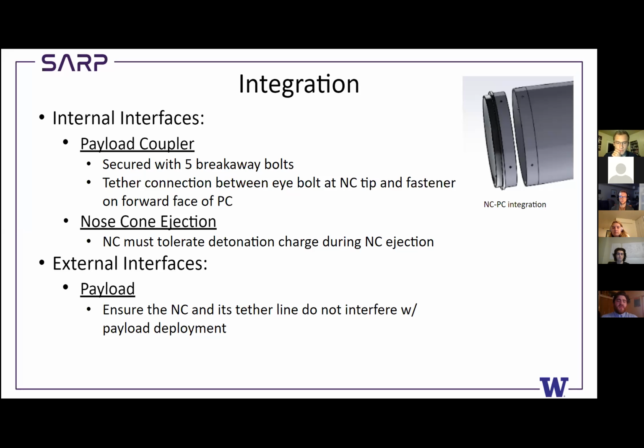Now, integrating with Nosecone ejection, the only design requirement we need to make really is ensuring that the Nosecone will withstand those pressure forces. As well, this isn't one of the bullet points, but it should be: make sure that the bolt holes on the Nosecone won't break or fail on ejection.